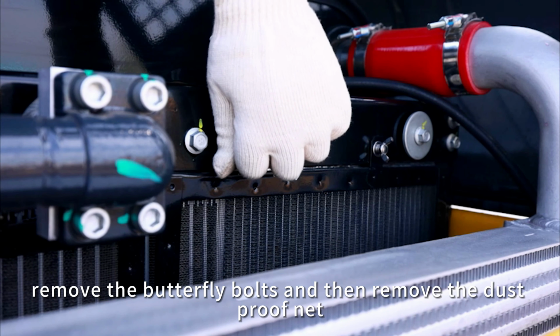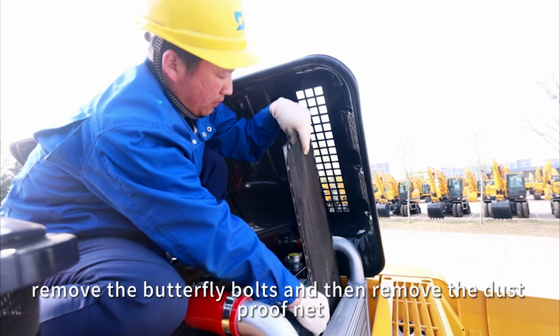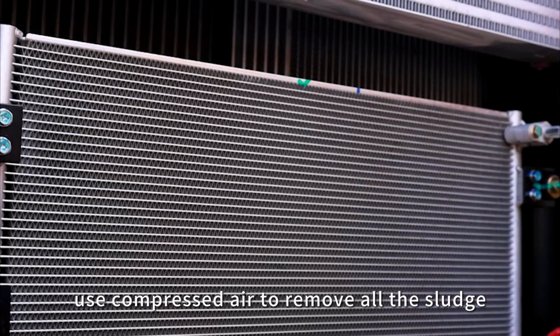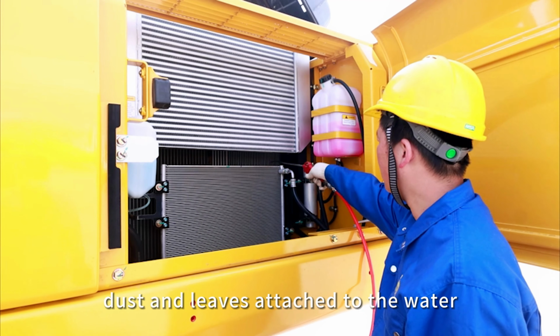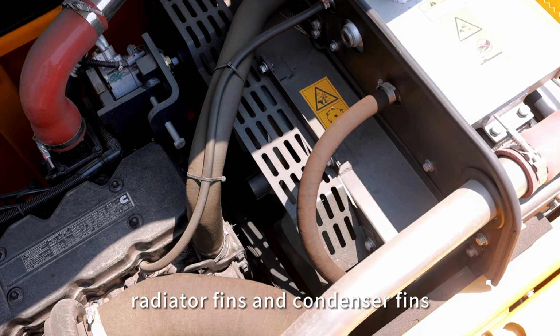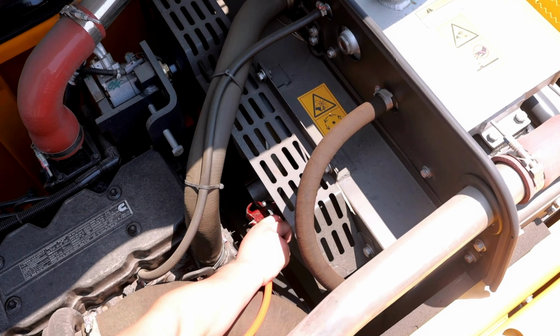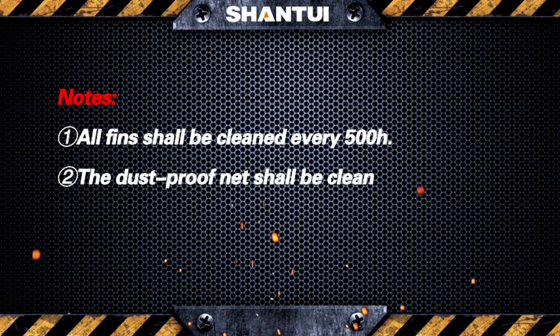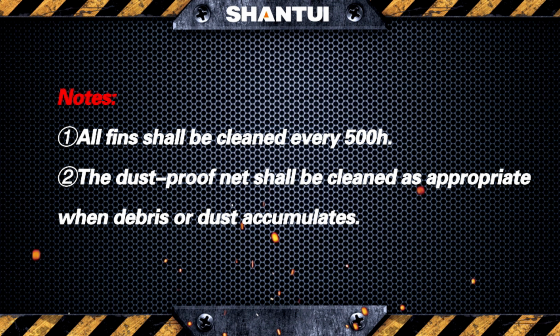Remove the butterfly bolts and then remove the dust-proof net. Use compressed air to remove all the sludge, dust, and leaves attached to the water radiator, hydraulic oil radiator fins, and condenser fins. Notes: 1. All fins shall be cleaned every 500H. 2. The dust-proof net shall be cleaned as appropriate when debris or dust accumulates.